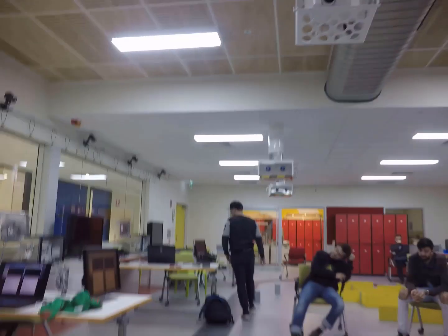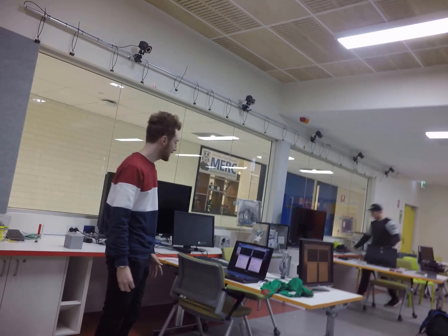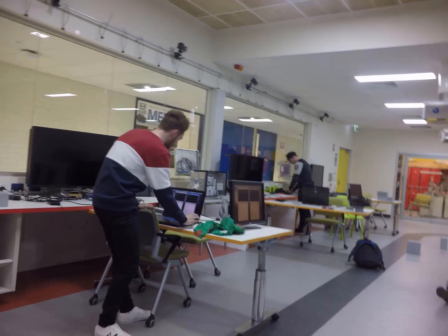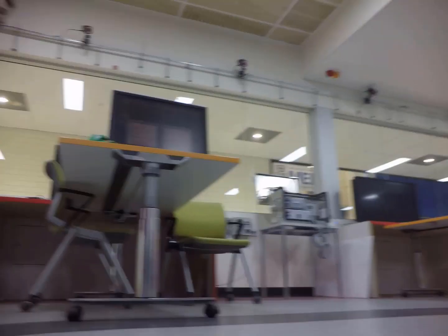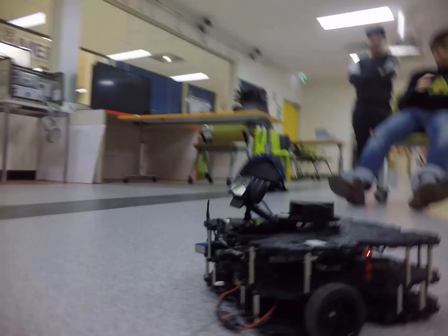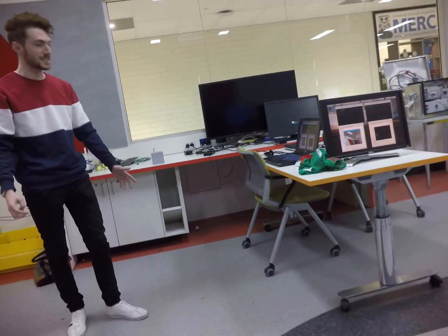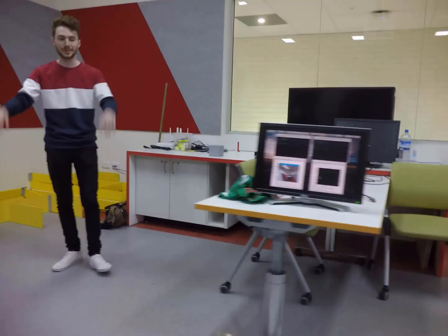So my project is basically human following based on the colour of the t-shirt that I was wearing, and I showed green for this. Two Python scripts on the TurtleBot, the first one does all my basic video operation with the MobileNet SSD Caffe model. We pick up a human, so basically I made it so that the robot will only detect people out of all the objects that it can, so don't worry about bottles, chairs or whatever, we don't care about them.